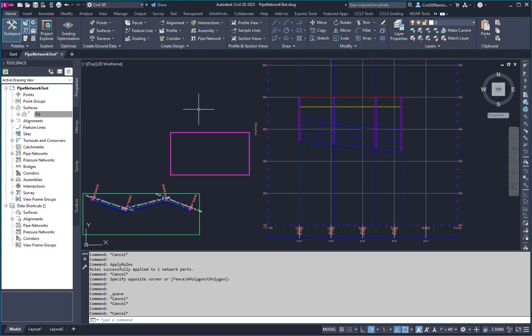If we have a rectangle, just to let you know, maybe someone from Autodesk is watching this, width is the distance across, in this case, for a structure, and I'll denote that as W. Height is measured in this direction, and I'll denote it with H. Right now, Autodesk is not acknowledging that there's a difference between width and height, and this results in a pipe network not being placed within the correct location if you pick a box culvert.